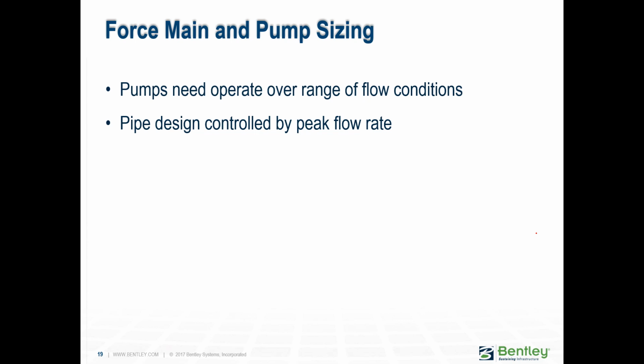Some other considerations. Whenever you're doing this kind of work for wastewater systems, just be aware that the pumps need to operate over a different range of flow conditions, right? Because your flows are not exactly the same from one day to the next, and within the same day, at night you get no flows if it's a residential area, so the pump is just not operating. But in the peak of the day, you might have the pump go on several times.